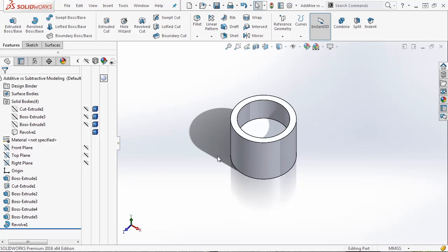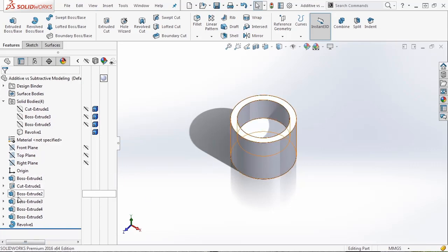Now, if you decide to do a subtractive type modeling where you start with the original block that you intend to use, start removing material, that can help you avoid mistakes by adding material that you can't machine or you can't get to. If you decide to do the additive, you have a lot more flexibility on how you can create that geometry. You will notice that we used the original sketch several times for the geometry we created, but we also were able to create a new sketch and do both the inside and the outside in one single feature without having to do an extrude and a cut or multiple extrudes to get that same geometry. So keep in mind the flexibility that you have when creating the same geometry in many different ways.